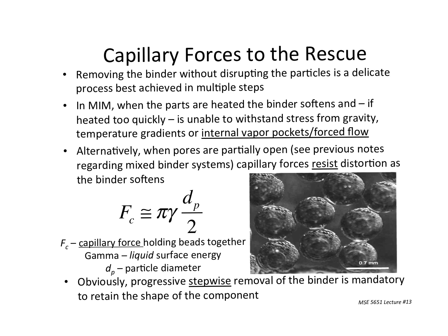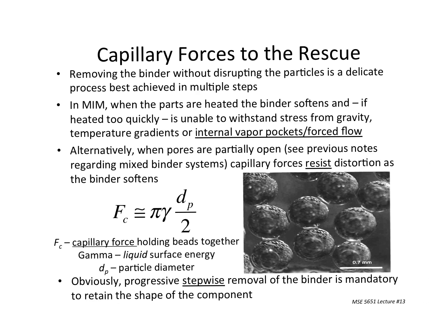Part of what makes this successfully function, along with not heating it too quickly, and along with not having the nanoscale involved in any significant way, is capillary forces in this context. We have to remove the binder without disrupting the particles, and in many cases this can be done in multiple steps.